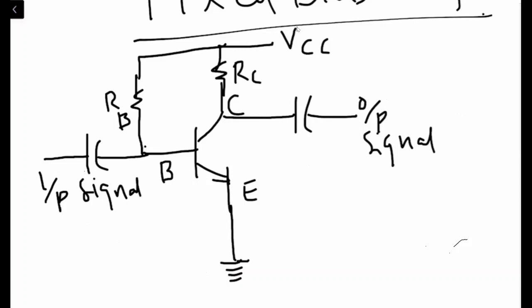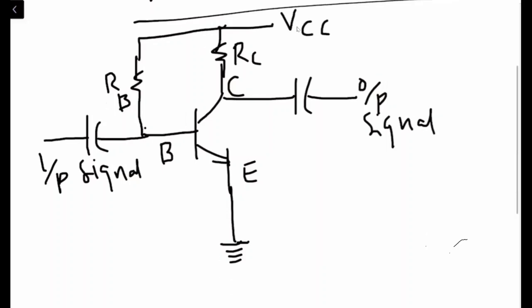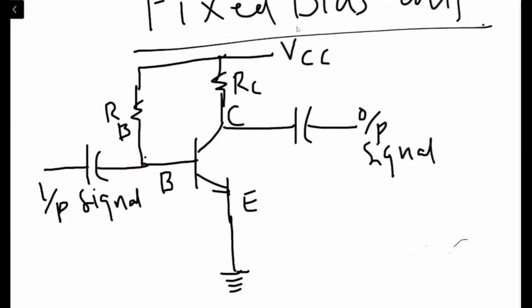So as we have started with the DC analysis, we need to make this circuit a DC circuit, right? So the first thing we need to do: if you can see, we have one capacitor over here which we call C1, which is at the input side, and we have another capacitor C2 over here, right? Now for the DC analysis, how do the capacitors need to behave, anybody?